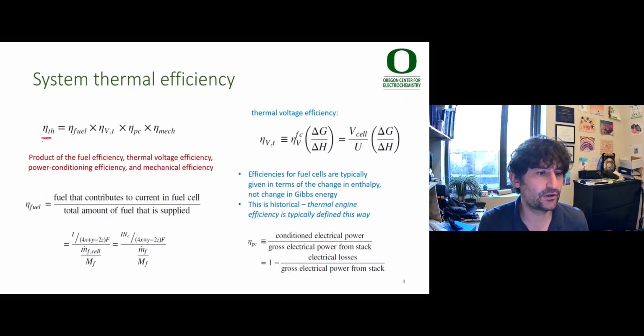The system thermal efficiency is just the efficiency of utilization of the fuel, we call it the fuel efficiency, times the thermal voltage efficiency, times the power conditioning efficiency, so how efficient are those power conditioning electronics, and the mechanical efficiency.